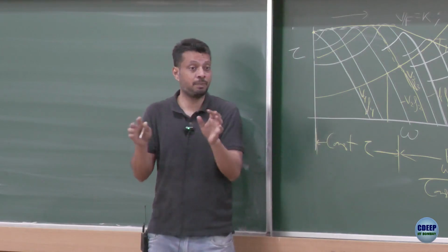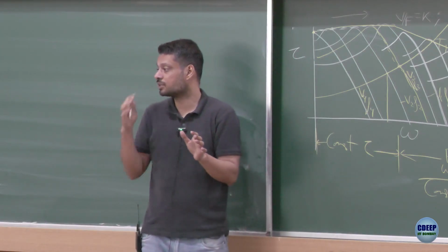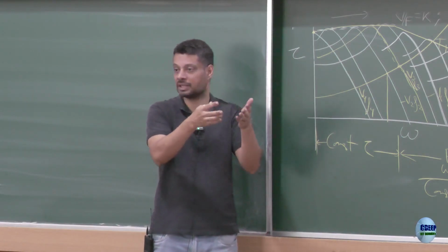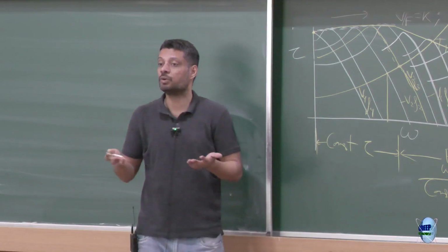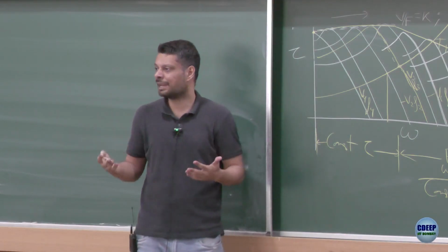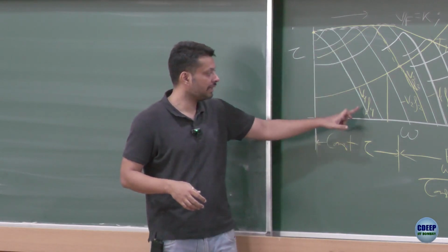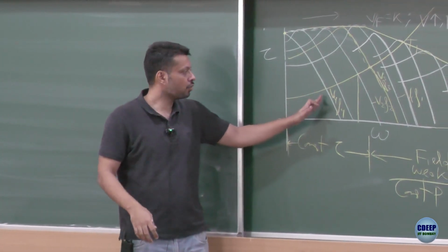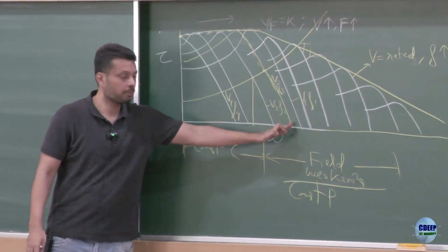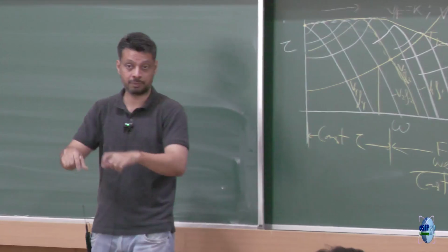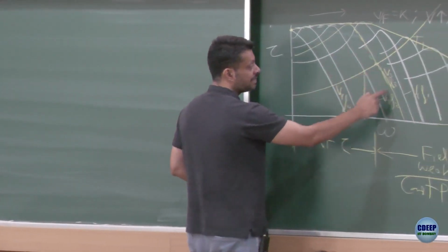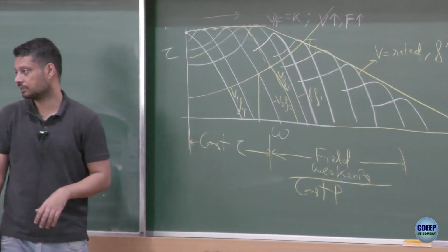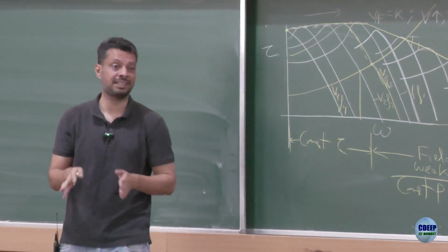That drive didn't have any speed feedback. If you remember, there was no connection to the speed. It was only connected to the 3 terminals, right? And therefore, it didn't actually know what the speed is. So from some calculations, some estimations, it would initially apply a very low frequency and voltage. And now it knows that the induction motor would have started. Then slowly it would increase voltage and frequency and take it up to the desired set point which you have set on the display. Now once you have reached the desired frequency, the speed would of course again depend on the load characteristic intersection, right. So this is how the drive which you were using in the experiment was working.